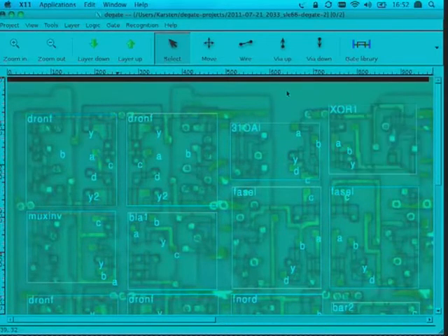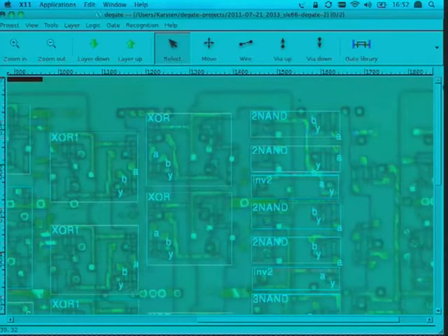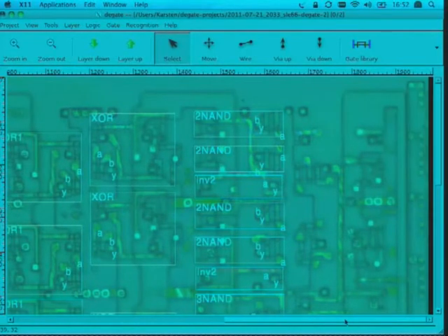We obfuscated this a little bit because we're not giving out the function quite yet, responsible disclosure and all of that. There's an AND gate. So some are just too simple. There's no obfuscation needed. There are 4 transistors. You see 1, 2, and another 1, 2. And they're connected in such a way that this forms a 2 NAND function, right?